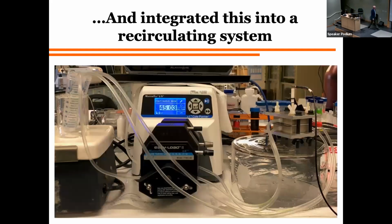And it looked like this. Here's that reactor. It's about that big. It's not very big, right? And it's got the influent lines for the cathodic side on top and the anodic side on the bottom, and that Nafion membrane's in there. And here's our reservoir. Then they're just sitting in a little bath of water so it stays at constant temperature. And what happens is you just get a little bit of reaction when the water flows through here. And so we recirculate it at a high rate. And so over time, the nitrate concentration or nitrite concentration drops, okay?